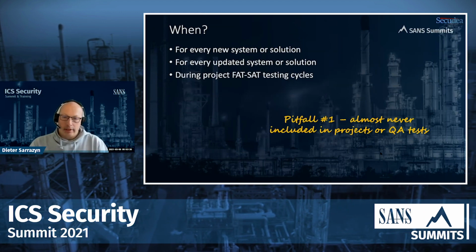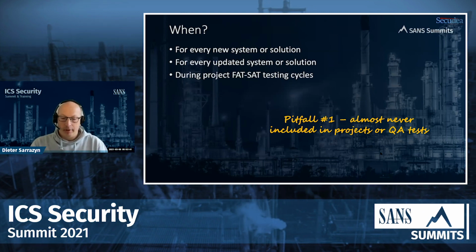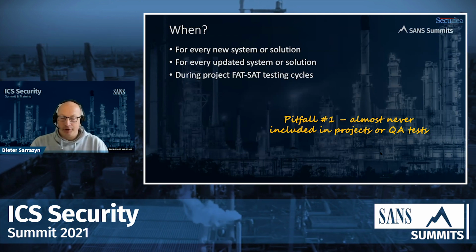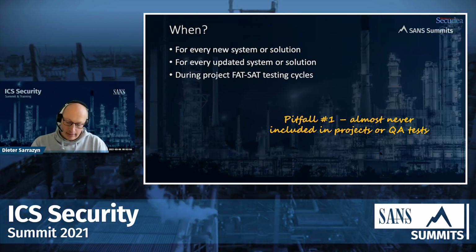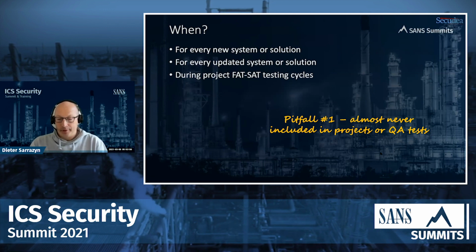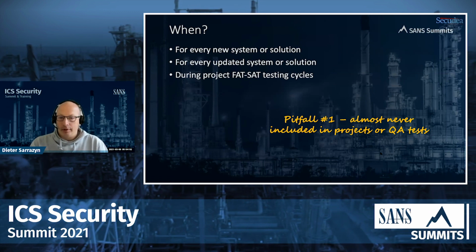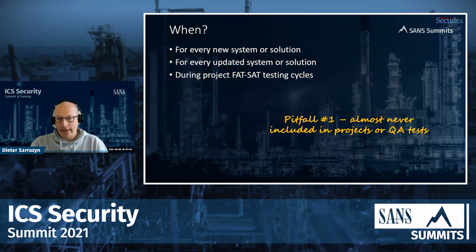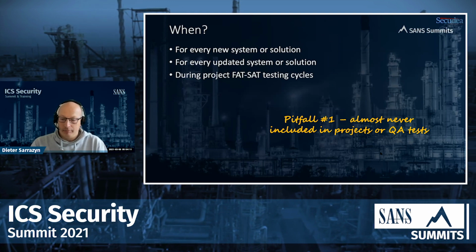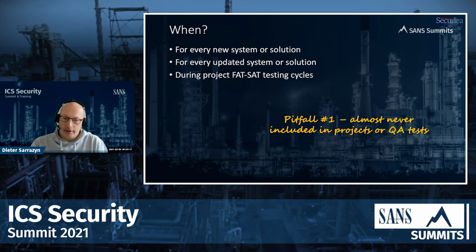When would you do cybersecurity FAT/SAT testing? Well, in my view, you should do it for every single new system. You should do it for every new or upgraded system, during project FAT/SAT testing cycles. So if you go back to the slide, when there's functional FAT and operational FAT, or sometimes also software FAT, it is often just not included within the project lifecycle, cybersecurity FAT/SAT testing. It is almost never included within quality assurance testing, and it should be, because cybersecurity should be looked at as a way of quality of the provided solution.